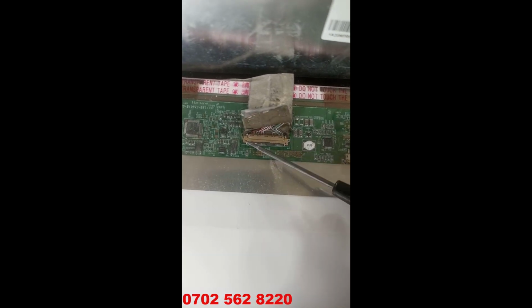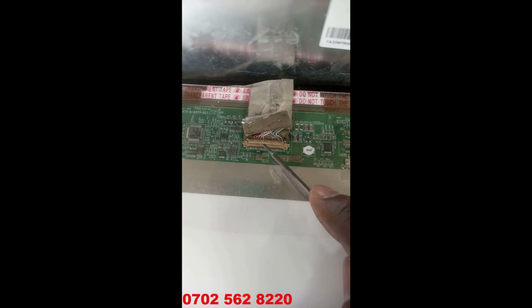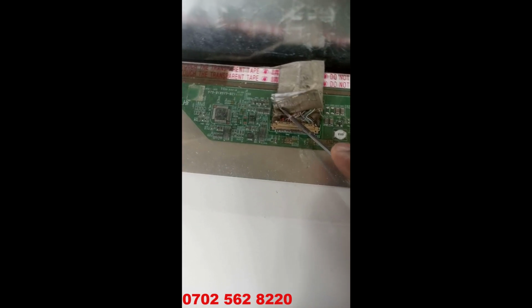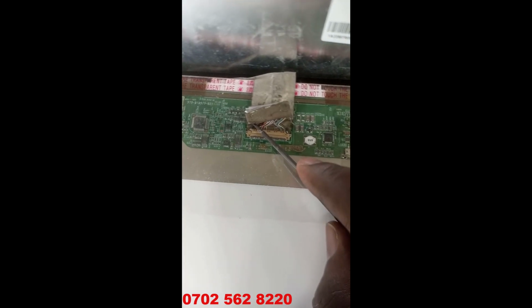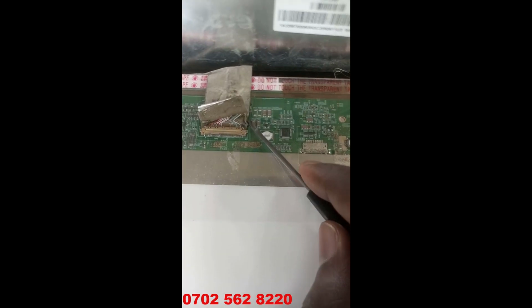Now, if you look to this other side, you will discover that there is also a rupture towards this side of the flex. There is a small flex here. How I wish my phone camera was very sharp so that you guys can see properly. There is a rupture on this other side of the flex, which controls the information. So these more or less are the data lines which have broken by accident.